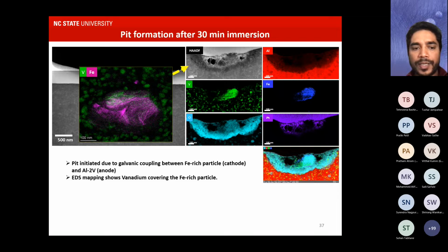So with that, I would like to summarize my talk. This is ongoing work, but what I wanted to tell you here is that we can really design these lightweight and really corrosion-resistant alloys by designing this far-from-equilibrium microstructure. You just need to choose a solute content which could prevent corrosion, and there are different mechanisms, right? We looked at those 4, 5, 6 proposed mechanisms, and find out which element can act as a species to inhibit the corrosion as it initiates, right? And then you can look at the strengthening by solid solution or grain refinement or both, right? And then you can really design these alloys.